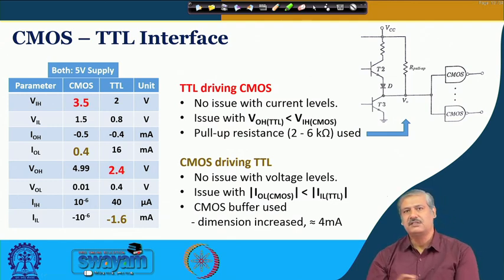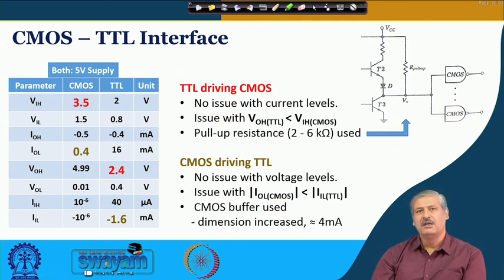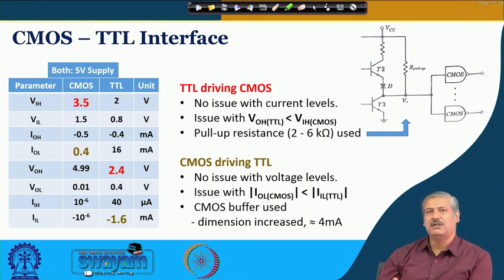Finally, last part of our discussion, okay, CMOS circuits are there, TTL circuits are there. There could be cases when for less power consumption, more packing density, we are preferring say CMOS, right, and for higher speed and associated benefits, we are thinking of using TTL, and then we want to connect these two parts for getting both the benefits.